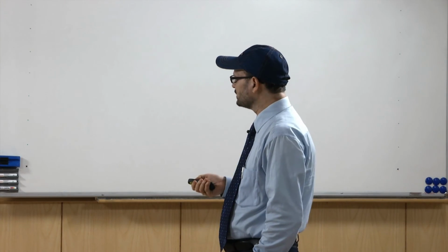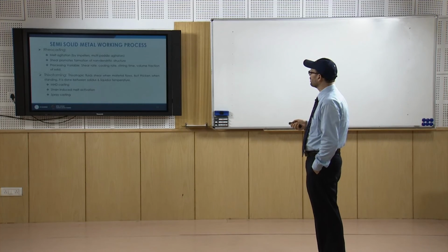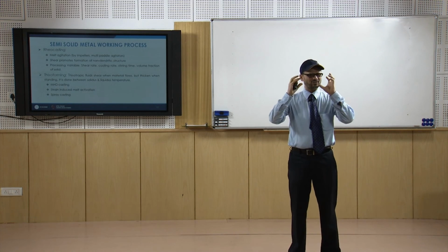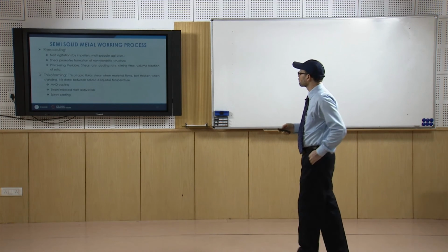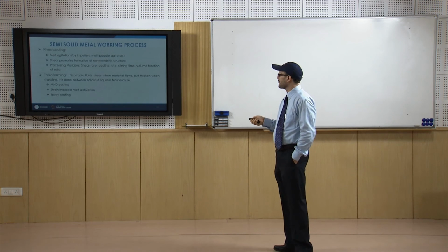Another kind of this process is Tixo forming. So, Tixo forming is based on the word thixotropic, which means that because of the shear the material flows, but it thickens when standing. So, when it is standing it is thick, but once you apply the shear force it will flow. So, it is done between solidus and liquidus temperature.